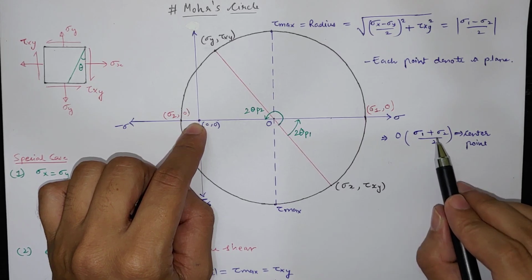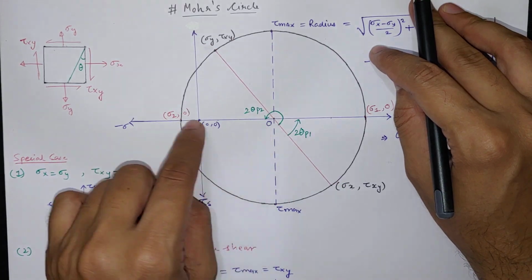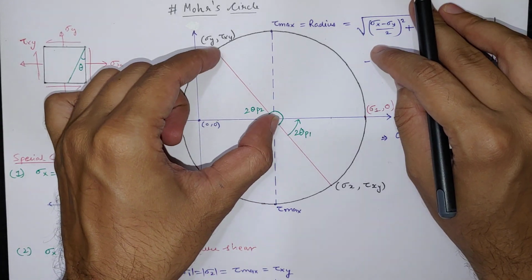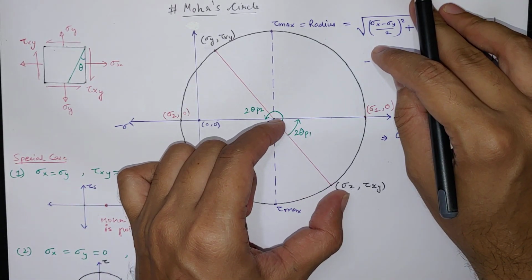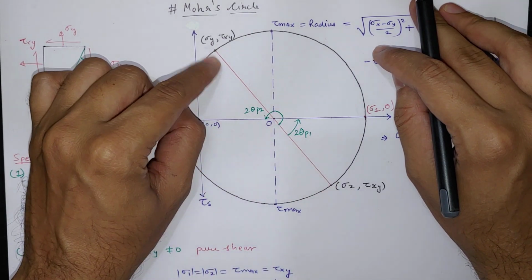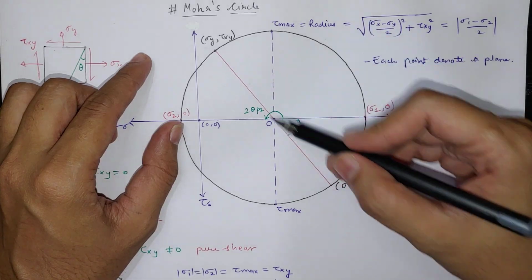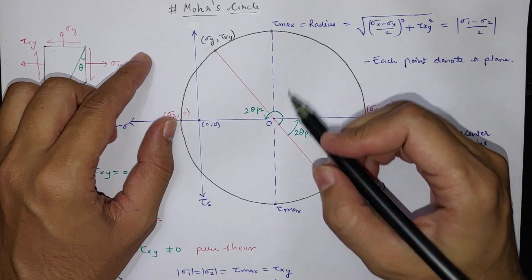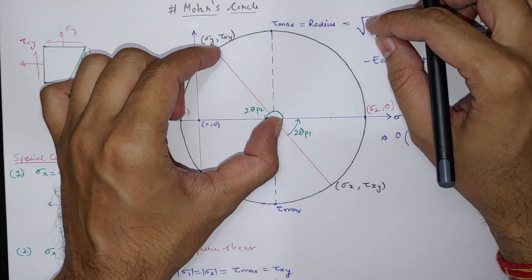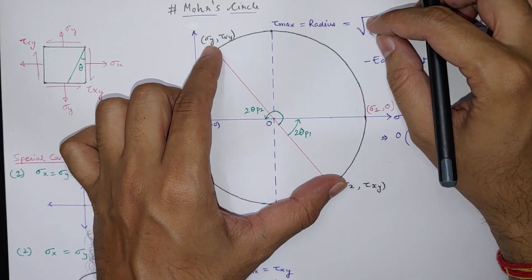So first we have to draw this line, and wherever it is intersecting on this horizontal line, that will be the center, and that will be equidistant from both these, because this is the radius of the circle, and throughout the length will be diameter. So now this will connect at the midpoint of this line with this horizontal line, and we have to draw a circle with this radius. Whatever the length we get, we have to draw a circle by keeping this as diameter.